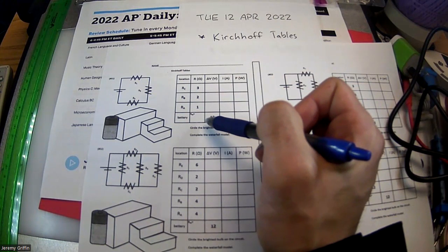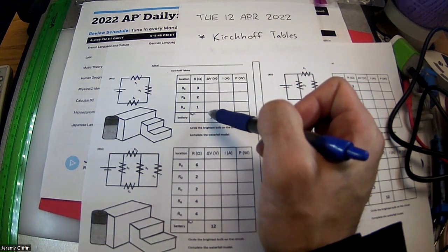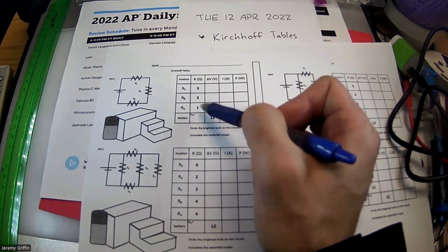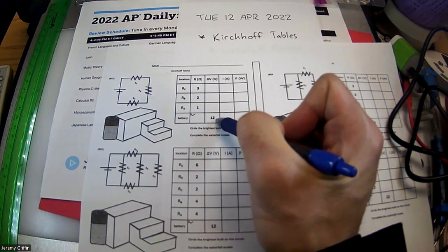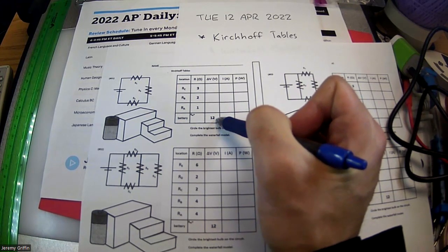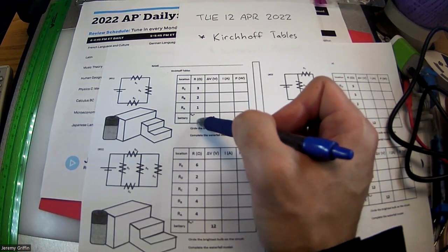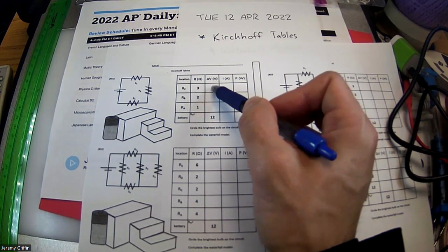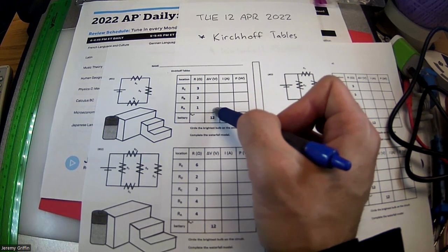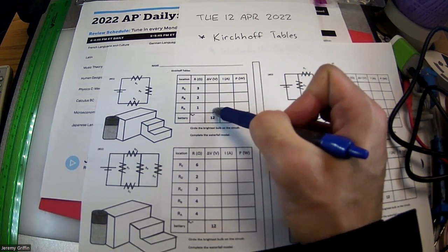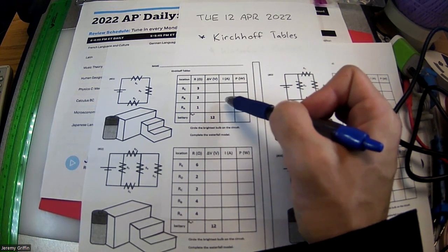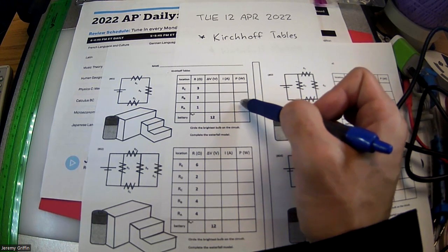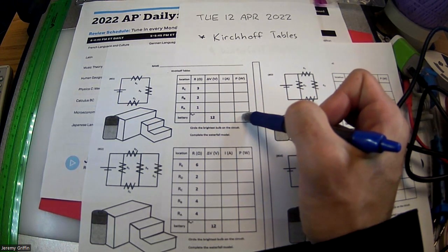Let's take a look at this table and figure out what's the layout, where we're going with the story. I told you what each of the resistors is in ohms. I also told you the voltage supplied by the battery, and that's everything I gave you. The first thing we're going to figure out is the equivalent resistance perceived by the battery, because the battery's pushing against some resistance. Then we're going to figure out the voltage drop across each resistor individually, the current flowing through each resistor using Ohm's law, and also the power across each resistor, like how many watts at each point.